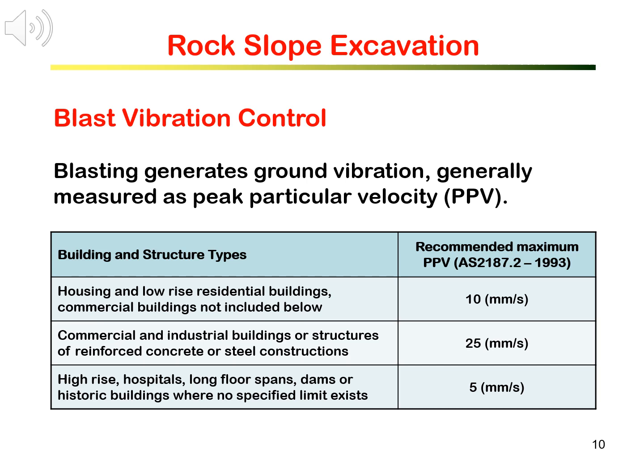Blast vibrations are usually measured and presented as peak particle velocity, PPV. The PPV limits for different structures are given by the Australian standards here. Other countries have the same or very similar standards for blast vibration limits. For example, if there are historical buildings in the vicinity, vibration from rock blasting reaching the building must not exceed 5 mm per second in PPV.